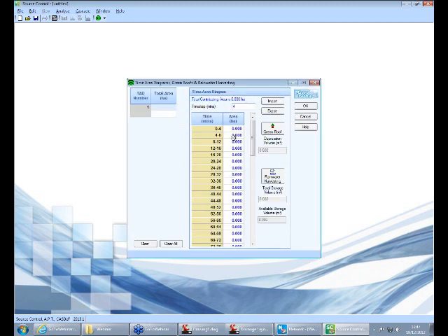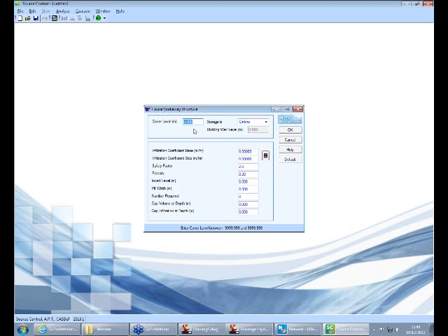The actual dwelling which we'll be sizing up, we're running the scenario that it may be a block of flats or something like that. So we'll say it may have a roof area of 0.05 hectares, so about 500 square meters of roof. One thing you may notice on the time area diagram form is the addition of the rainwater harvesting features. It's something we'll come back to in a minute, so we just size up the structure first so I can show you some of the new outputs we have on the summary of results. So go OK, a time area diagram, and it pops up our house soakaway structure.